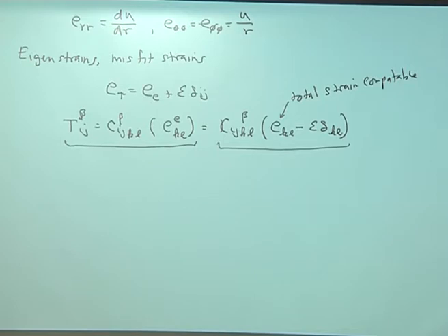And someone already corrected me on my definition of the misfit strain, right? The reason why the alpha sits in the denominator is because we're using the alpha phase, the matrix phase, as the reference state for strain. The thing that has to be compatible, since Eij has to be compatible, what that means is that this is the thing that's related to gradients in the displacement.